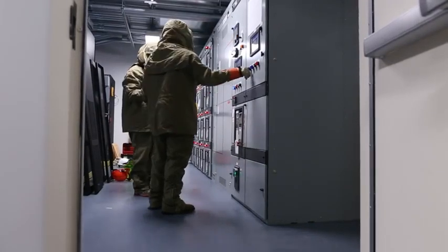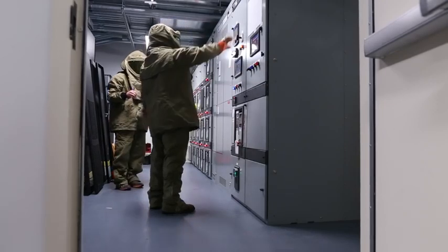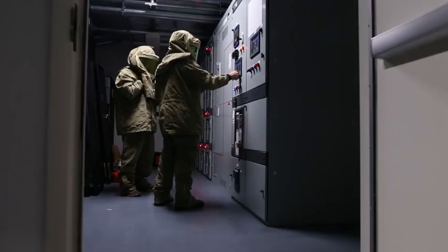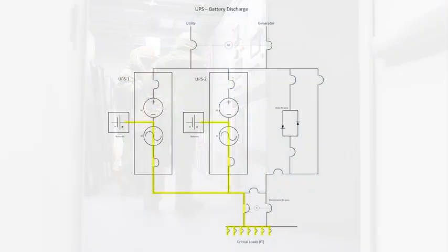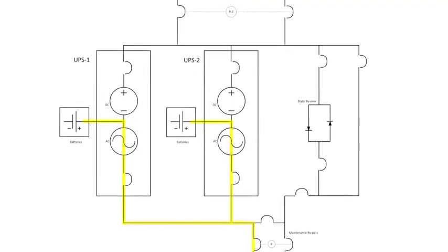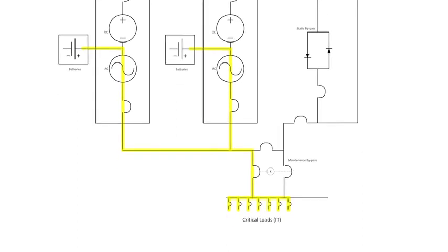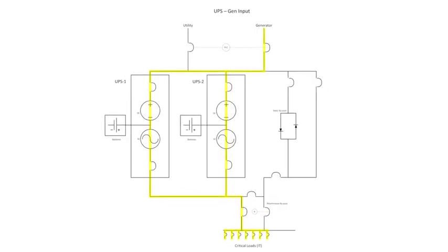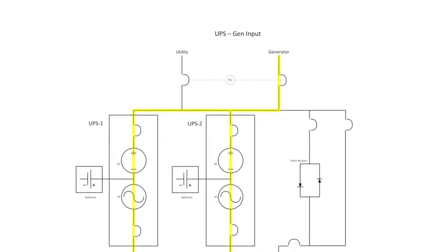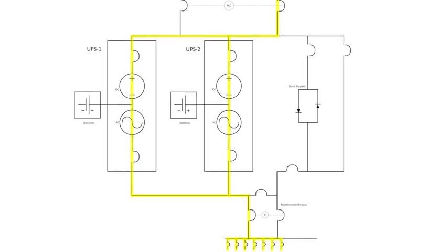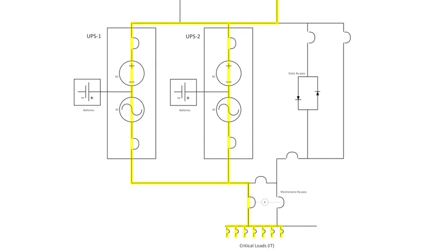The transition takes approximately 3 seconds to transfer load. During this time, the batteries will provide current to the critical IT load as illustrated. Once the transfer is complete, the load is now supported by the generators. As illustrated, electrical power is still flowing through the UPS modules. The UPS modules are not yet safe to work on.